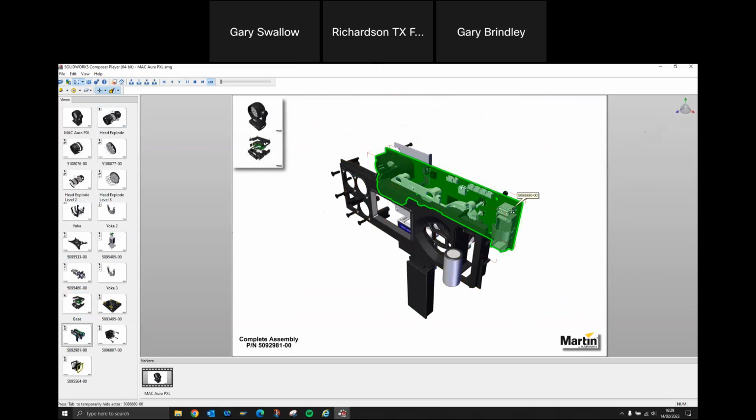And through some fate or something, that part number is actually available for purchase for some reason. So they're purchasing the wrong part, they're receiving the wrong part. Obviously, we're trying to mitigate and avoid that now, but it has been known that people have ordered the wrong part number and received that exact part number, and it has arrived with no firmware on it, and they can't load firmware because the bootloader doesn't exist, that sort of thing, because it hasn't been through the production process of that part needed.